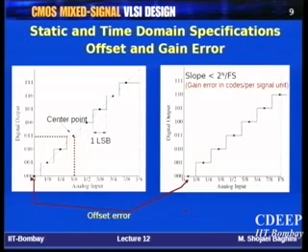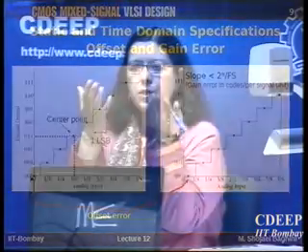What eventually the ADC does is compare the analog input with some reference values, right? And then if that reference value is below the signal, we will go to the next code. The next code will be generated and so on. So if you look, this comparison itself may have some error, right? When you compare two signals, you are comparing x1 with x2.